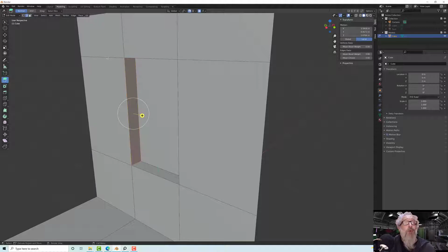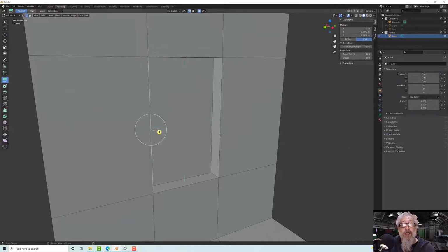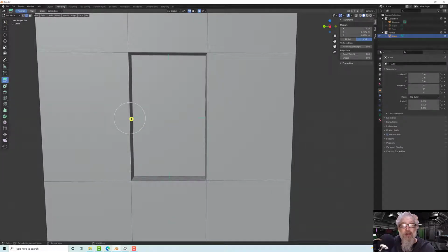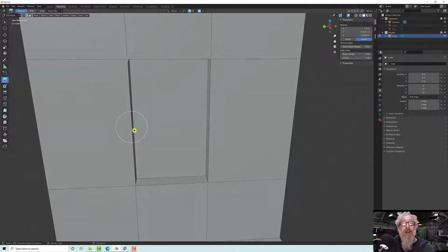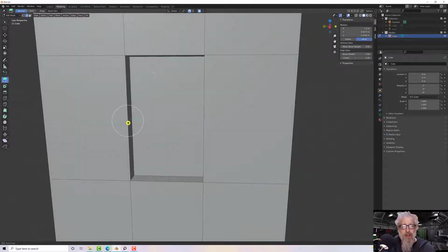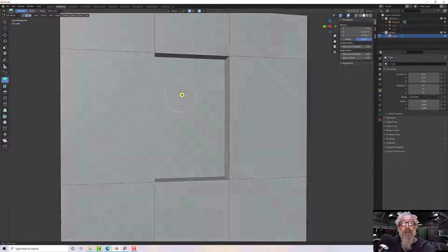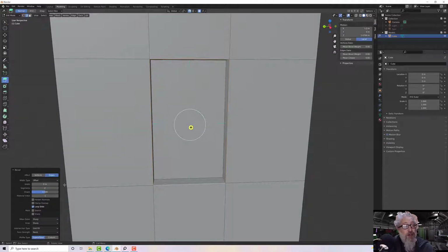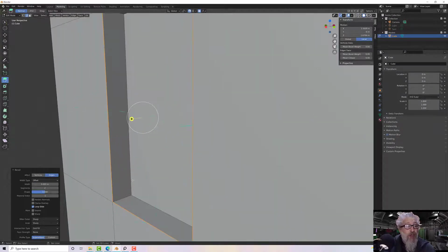And now I would want to bevel these edges, because having that sharp edge there is not going to look good. But if I press Alt and click on there, it's not going to select all the way around, because the geometry flow doesn't know which way round I want to select. It could be anywhere. That's because I have essentially 4 edges at each vertex intersection. So if I do happen to manually select around here and then use bevel with Control and B and just click in to start it off, I'll give it a 2mm bevel and 2 rounding levels or 2 segments.